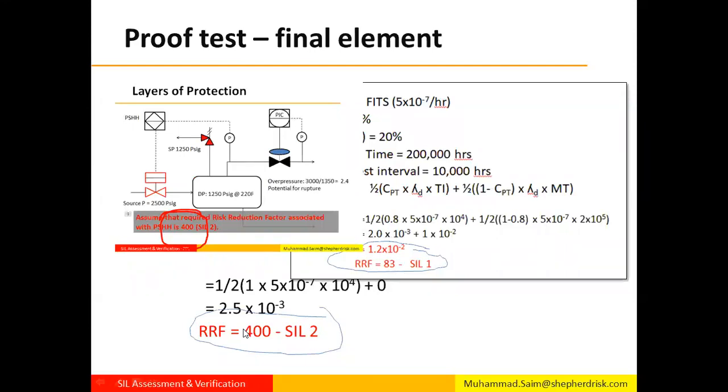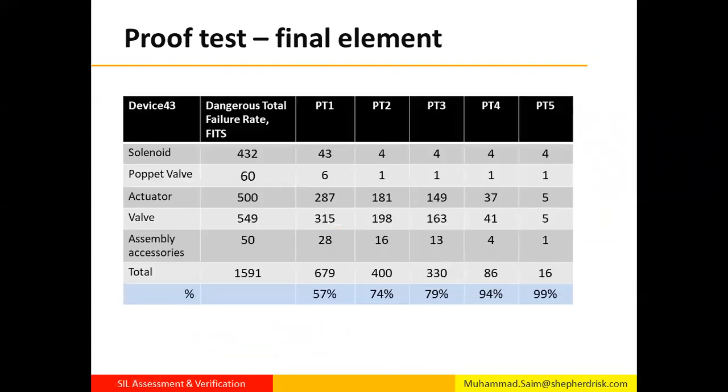But is it practicable? So now we ask our operations and maintenance teams, do they allow to carry out all the 5 proof tests on the ESD valve? So we know that in most of the continuous processes in industries which operate 24 hours, 365 days a year, we do not normally allow online full valve stroke tests.